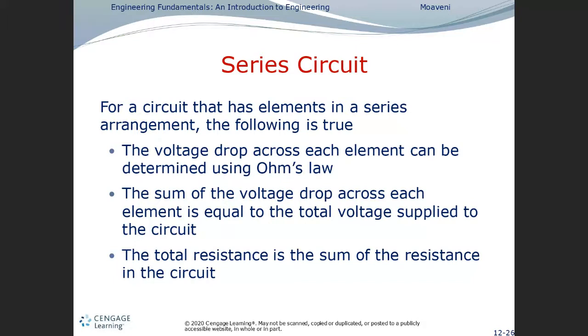So if you're trying to choke the flow of this current, put in more resistors in series, and you're going to reduce the current throughout that circuit, right? And so when I ask, what's the total resistance? You'll just say it's the sum of R1 through R5 if you had 5 resistors. That's how you would get the total resistance.